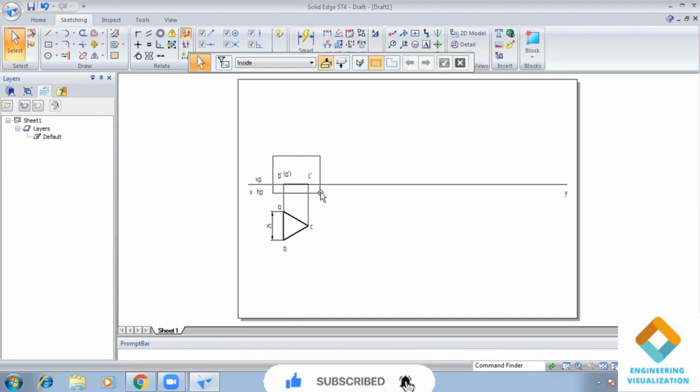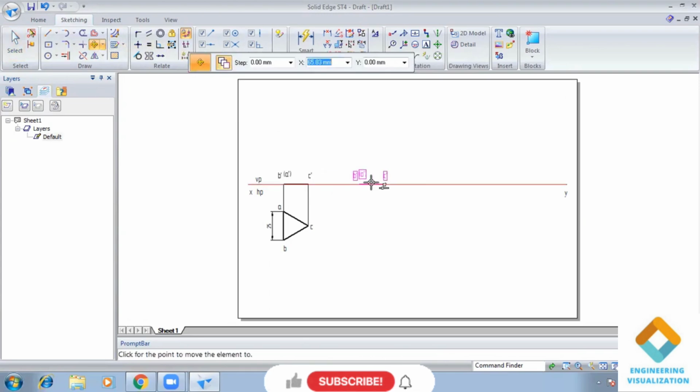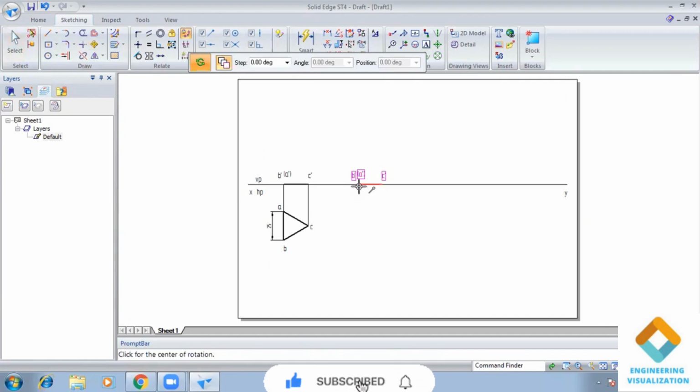Now select the front view. Go to move command. Create a copy of it. Slide along the XY line. Okay. Now go to rotate. Okay, select the one end. So before doing it, unselect the create copy, because it will create many number of copies.